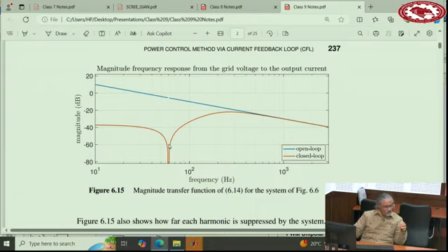That also removes the grid voltage as a disturbance, even though we put in a feed forward anyway. The feed forward takes care of removing that disturbance. The reason we use it is because we want a soft start and current limiting, but the controller itself also removes it in the steady state.